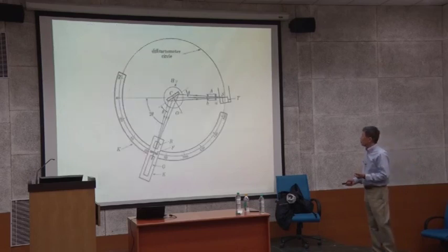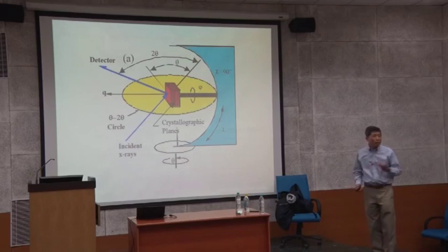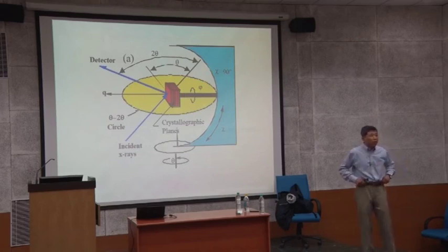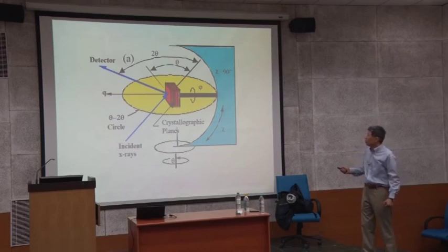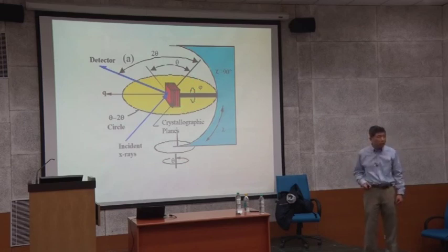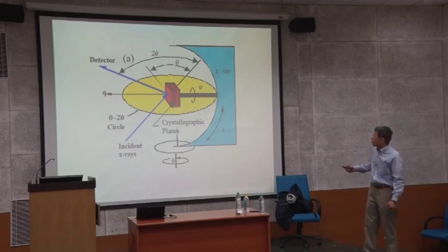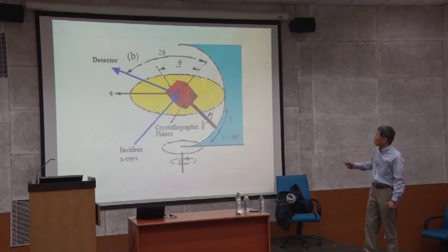But in actual thin films, you need to access all of those. So you need to use what we call full circle X-ray diffraction. In order to access this, you mount your sample, and this is the actual theta, the motion of theta. But you mount your sample, you actually spin this, and you can lock this one. Okay, so locking this one, this is called phi, and this one is chi, you have a chi angle.